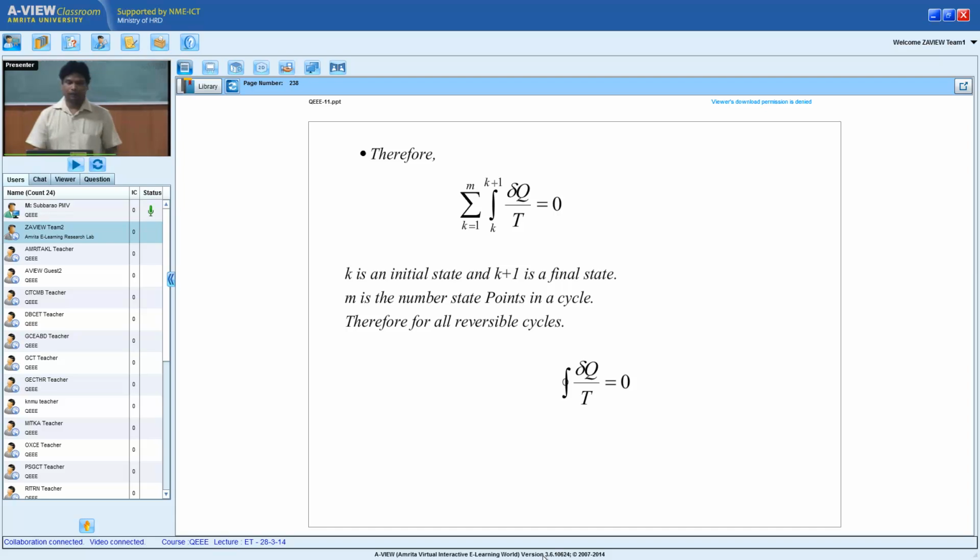One question is, in an air standard cycle, the efficiency depends on the compression ratio. Why? Because the higher the compression ratio, you can create the highest temperature with the same amount of fuel burned. That is the beauty of this. If you have a lower compression ratio, you are burning the same amount of fuel, but your highest temperature is lower. Very interesting. So in an air standard cycle, the economic way of achieving the highest temperature is to increase the compression ratio. Or in a Brayton cycle, increase the pressure ratio.